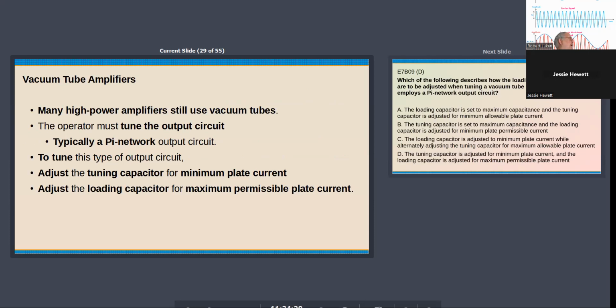So where would a class C amplifier work well? It doesn't ask that question, but that's a good question. They do use class C amplifiers, but what would be the application of a class C amplifier? Would it be CW? Yeah, CW wouldn't care much about the nonlinearity. We talk about modulation being amplitude oriented, which is sideband and AM, but CW is just a fixed carrier.